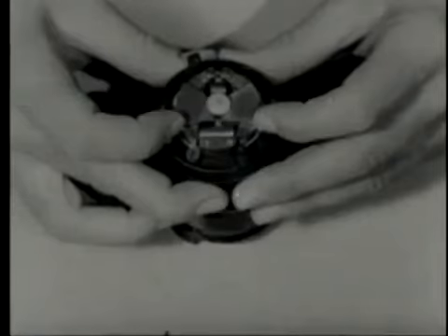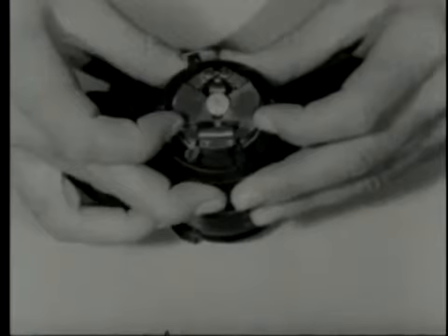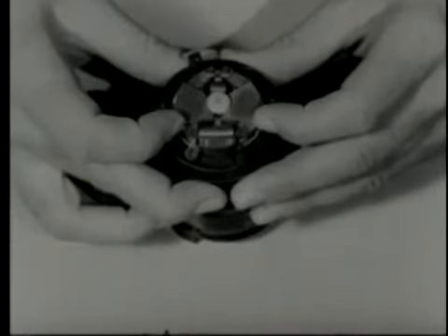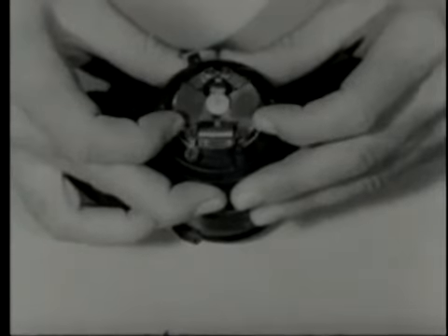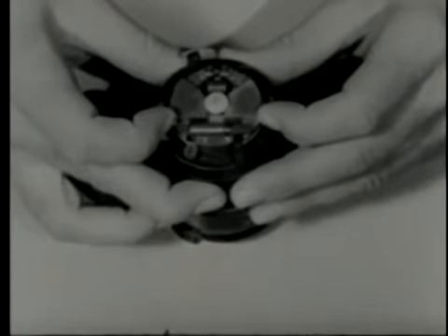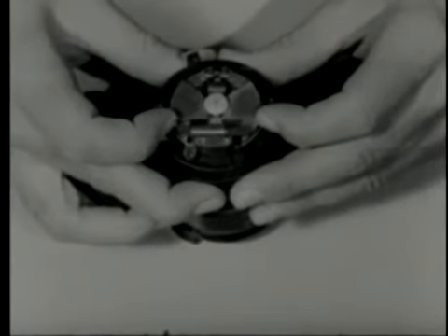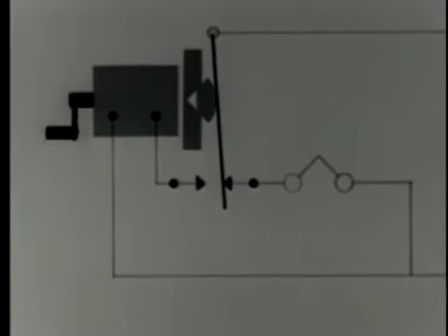A rotary action exerts a centrifugal force on the counterweights in the generator. As the counterweights are spread apart, a movable button drops down and makes contact with and closes the generator circuit. As the counterweights come together, the button raises and makes contact with and places the ringer on the line. This is how the generator switch works in the circuit.